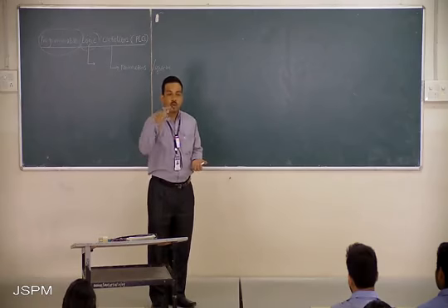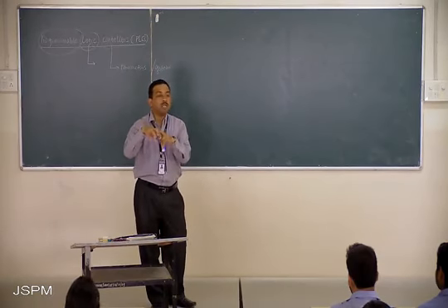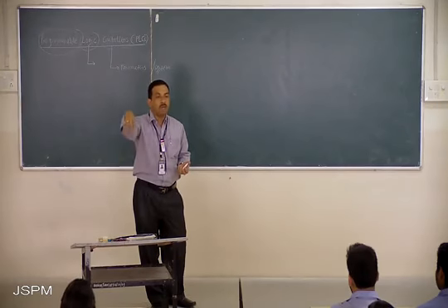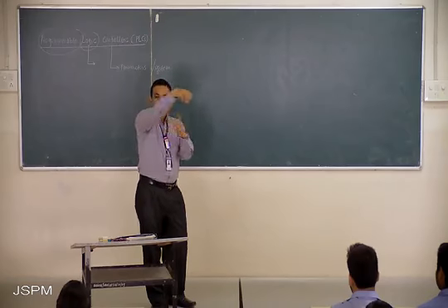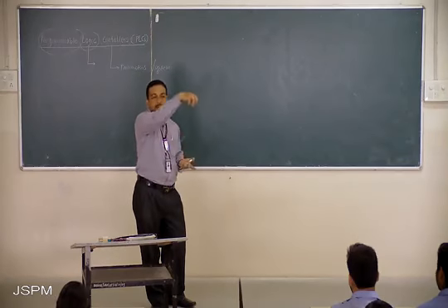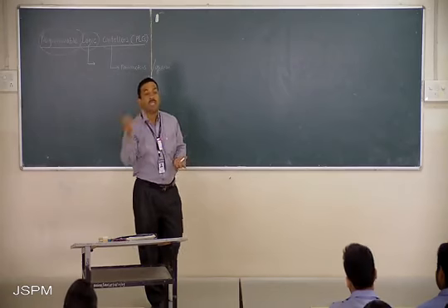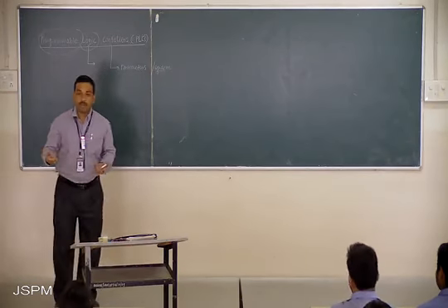Right. So the robot arm is equipped with a sensor. That particular sensor will detect the position of the object, and that object will be picked. Then as per the programming provided to it, it moves through a particular distance and angle, drops the material, and again comes to the original position. So automation is recommended where repetitive actions are there.